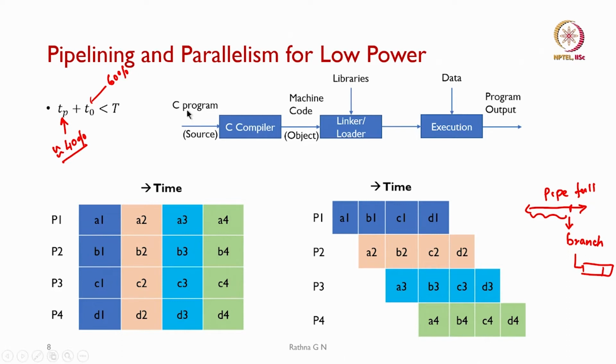Then how are we going to write our code? Most of the time we said we will use C programming. Most of our applications we discussed were both in MATLAB and in the DSP processor, and we concentrated only on C programming. We did not have time to do assembly programming. Those who are interested can go through the textbooks and work on assembly programming. We have the compiler, and compiler options for branching and other things, with which one can optimize up to 3 levels. They give it as O1, O2 and O3.